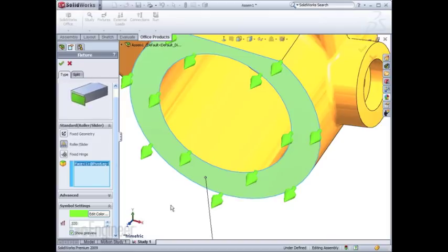We also have rotation about the X-axis restrained because essentially you can think of 2 points on opposite sides of an axis running down the length of this face. Those are also restrained. However, rotation about the Z-axis is not restrained.